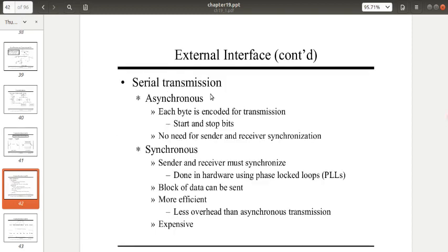Now coming to the specifics of serial communication. Like I mentioned before, there is asynchronous and synchronous communication. The names synchronous and asynchronous come from whether the clocks of the devices are in sync, right? That is, whether they are using the same clock. If it is synchronous communication, it means that the clocks of both the devices are in sync,